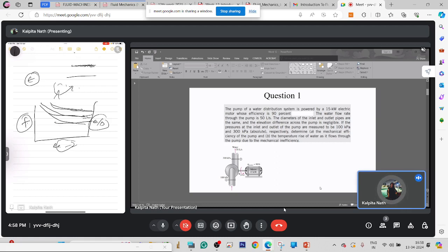Thus, the outer flow is exposed to the wall roughness, as the viscous sublayer becomes thinner and thinner. The form drag is very important when the surface roughness protrudes into the outer layer and the viscous sublayer is very small. When the form drag is dominant and Reynolds number is very large, the friction factor is almost independent of Reynolds number, as form drag dominates, not the skin friction drag.